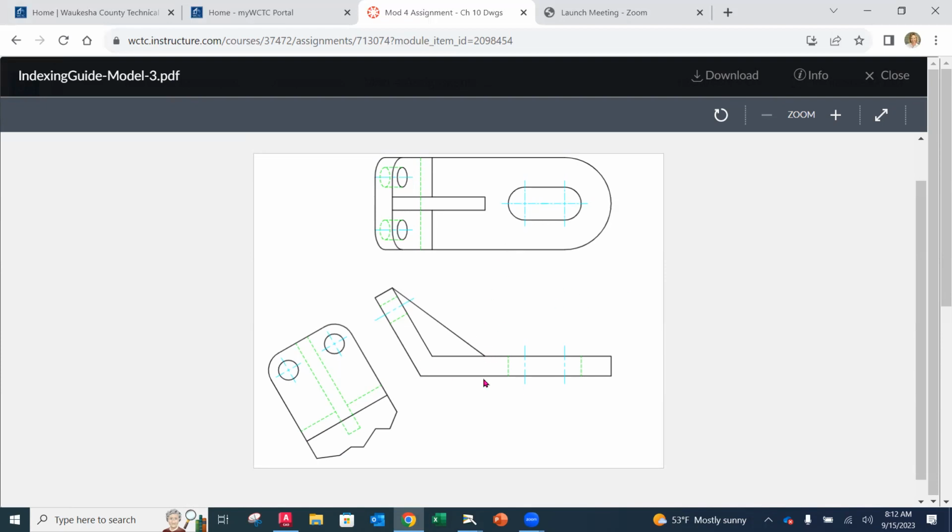So you'll notice we have a front and we have a top view. Now, I didn't add a right side view. You could if you wanted to, but as we get into dimensioning, this is also going to make more sense. We have to make sure that we show every feature in at least one view where we see it as true size and shape. And we end up doing that for this part of the angled surface in that auxiliary view. So this ends up being our third view instead of having another primary view that we can't dimension.